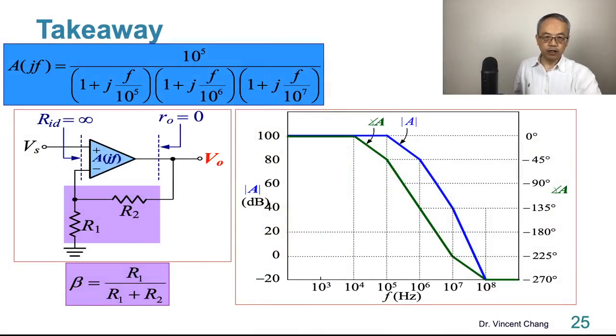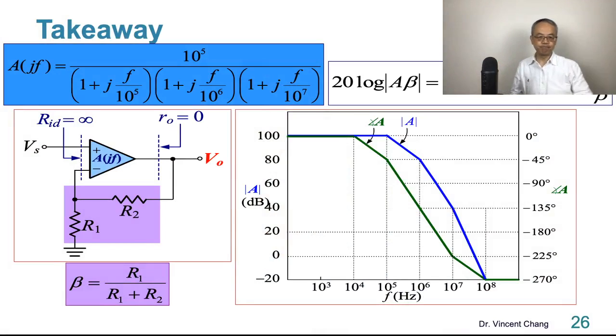So when an open loop transfer function, for example an operational amplifier, is given, but you have several different resistive feedback networks and you want to evaluate which one fits, you want to evaluate the stability for one operational amplifier but different resistive feedback networks, different beta, then you can apply this.